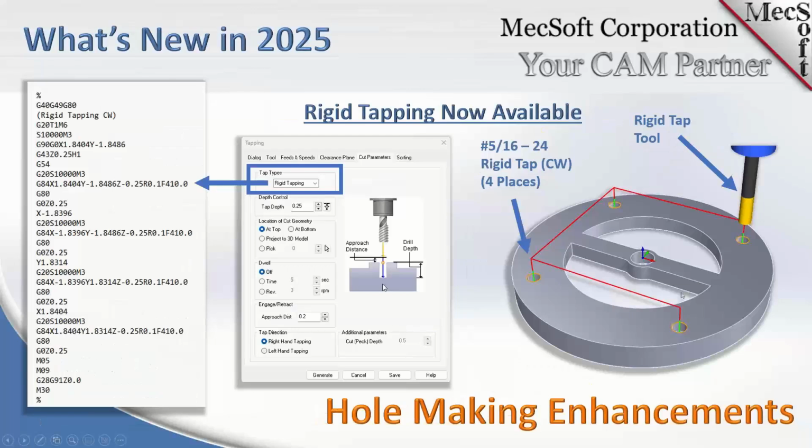Now we're going to go from 5-axis to hole making because we've added a new hole type method, and that is called rigid tapping. Rigid tapping is available if your CNC controller supports what we refer to as canned cycles, as in a can. These are predefined cycle types in your CNC machine that you can apply as needed. This is an additional cycle type that we've added. It is a G84 cycle.